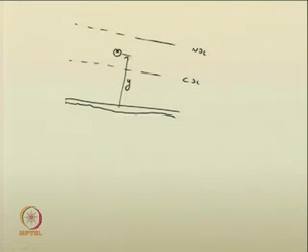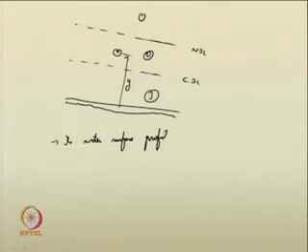So, at this stage this is in zone 2 of the water surface profiles. The water surface profile, that is the gradually varied flow profile at the entrance to the Malta town in that channel, is an M2 profile, because it is a mild slope channel and it is in the second zone. Therefore, it is an M2 profile.